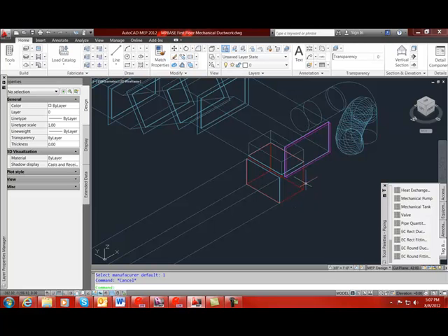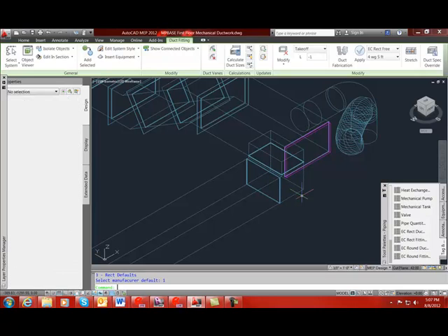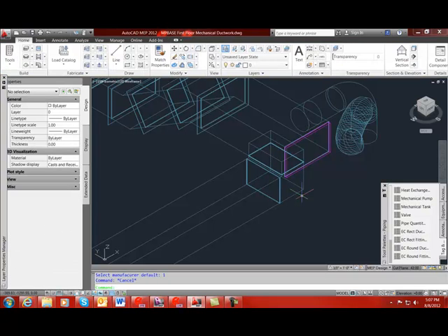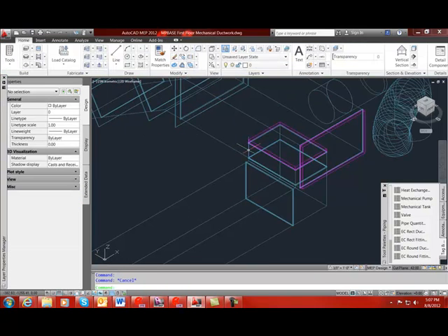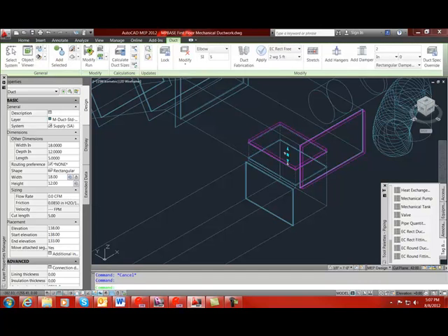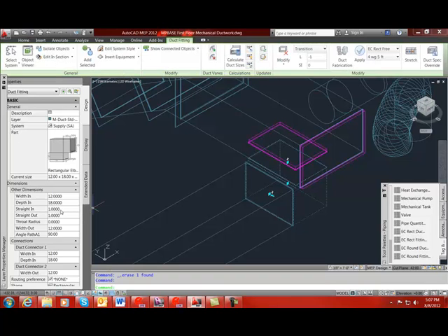We're going to do the same thing now to the elbow square: EC Rect Free, whatever specification you want, and apply. The next thing to do is set the length of the tap to 1 inch, making enough room for the square elbow to have straights of 6 inches. We're going to delete the piece of duct in between the tap and the square elbow. Now we're going to set the straight in and straight out on the square elbow to 6 inches each.